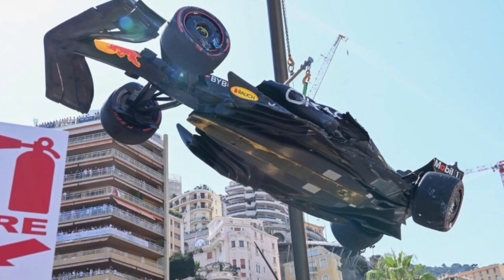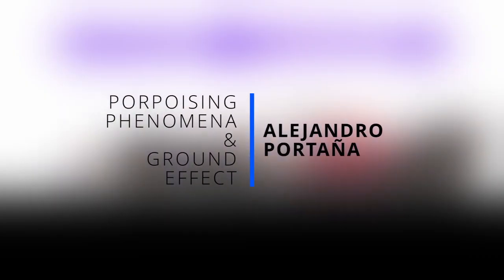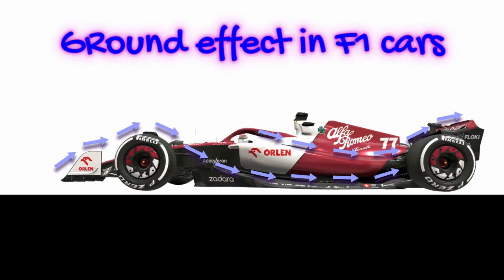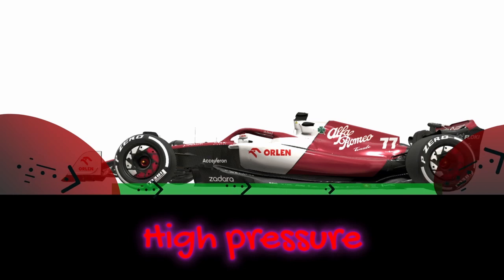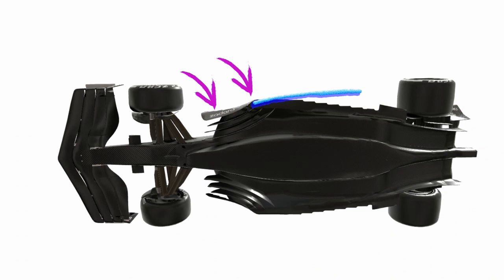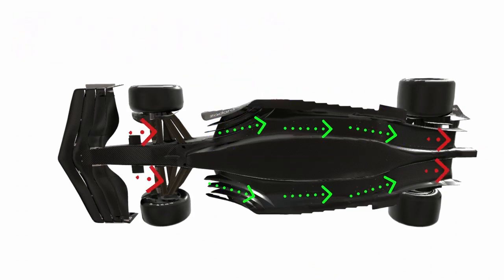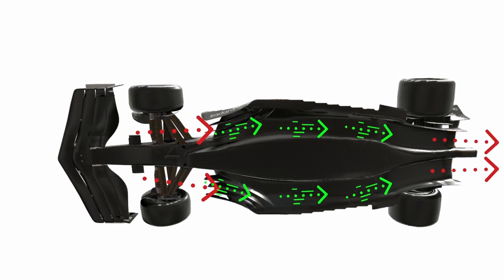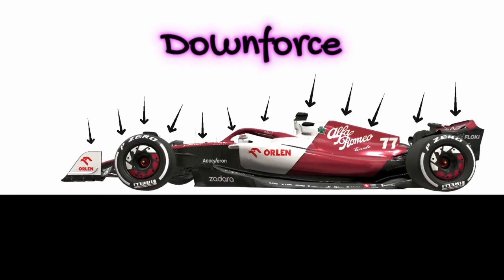New ground effect strategies aim to use floors like the one we are studying in this video. The ground effect in race cars is caused by how the flow interacts with the aerodynamic surfaces of the car, but more importantly the floor. The floor generates a high pressure zone and a low pressure zone just under the car. This happens thanks to the Venturi channels and the geometry of the floor of the car, which are responsible for lowering the pressure and accelerating the flow. This accelerated flow generates a force called downforce, which is actually pushing the car into the floor and giving some extra speed to the car.